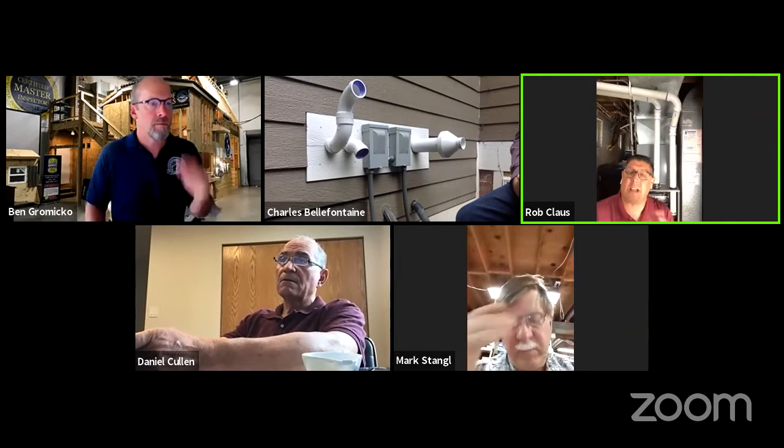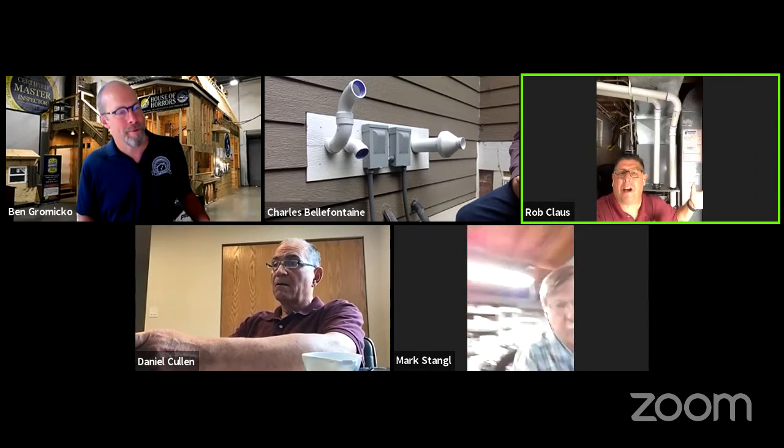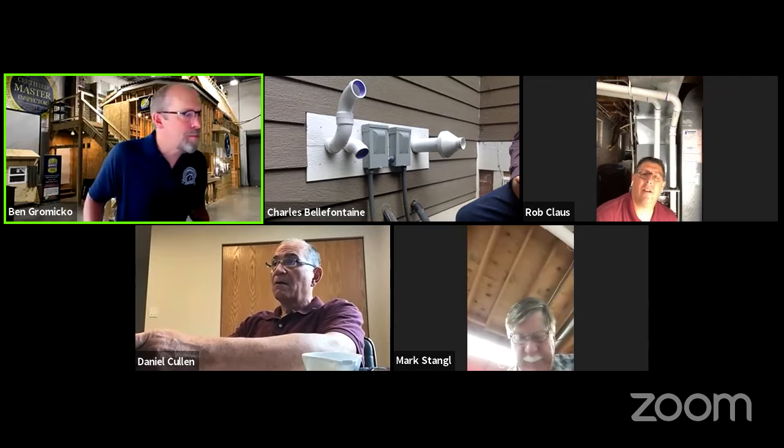However, an interesting tool, because I like to make my stuff very visual: your phone case and a simple flame mirror. I can take a picture of escaping flue gas from a natural draft diverter by looking at the cloud, and say, flue gas is escaping. I'm not going to tell you what it is, but it's flue gas.